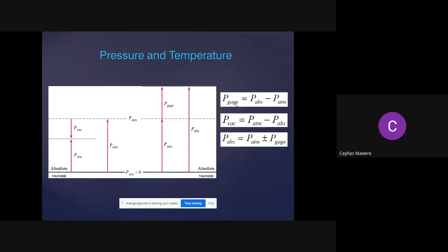But pressure comes in different types. We've got gauge pressure, which can be measured. We also have absolute pressure. We also have atmospheric pressure. So absolute pressure can be determined. It can also be measured based on the knowledge of the gauge pressure. Atmospheric pressure can be calculated. It can also be set as a standard. So gauge pressure can be calculated as absolute pressure minus atmospheric pressure.